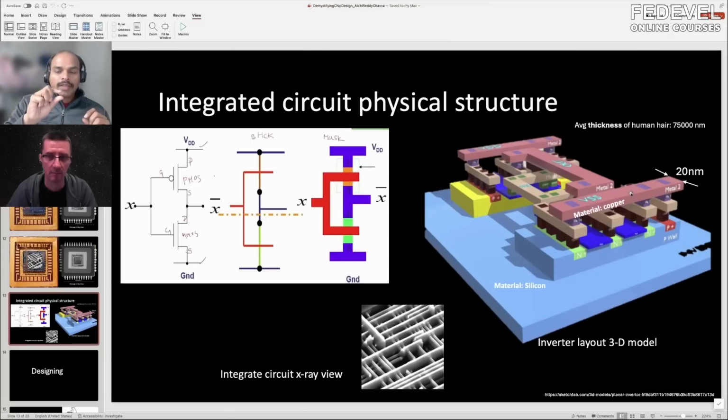So I need structures which have good electrical characteristics. That's the reason why, as we go up, we use wider structures, because there is no reason for them to be thinner. They are far away from the device in the vertical direction, and they have better electrical characteristics. Yeah, we use that, and then to the point B.